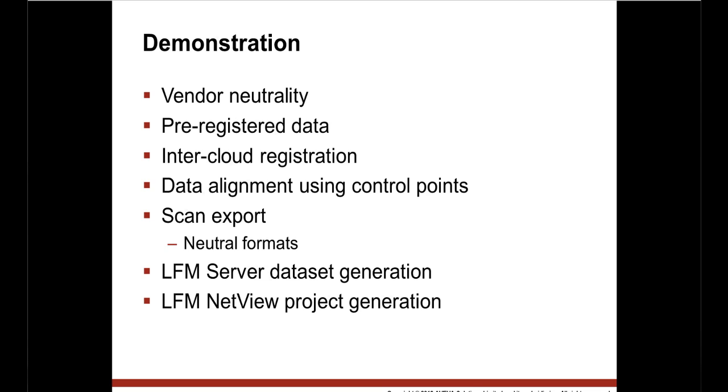So LFM supports scan formats from various scan vendors, even in pre-registered format. As mentioned at the beginning, we aim to be open on the inputs and open on the outputs. We also saw the ability to manually manipulate scans and then perform intercloud registration on the scans to register without a survey. In addition to the intercloud registration, we also aligned the data utilising control points. As you saw, this is a very easy process.